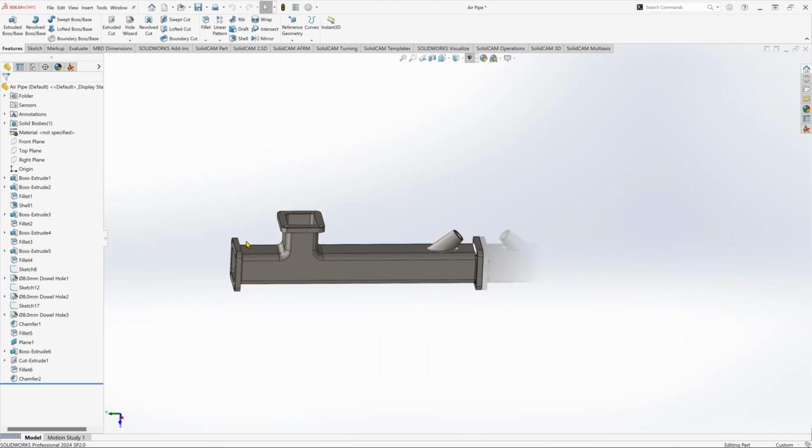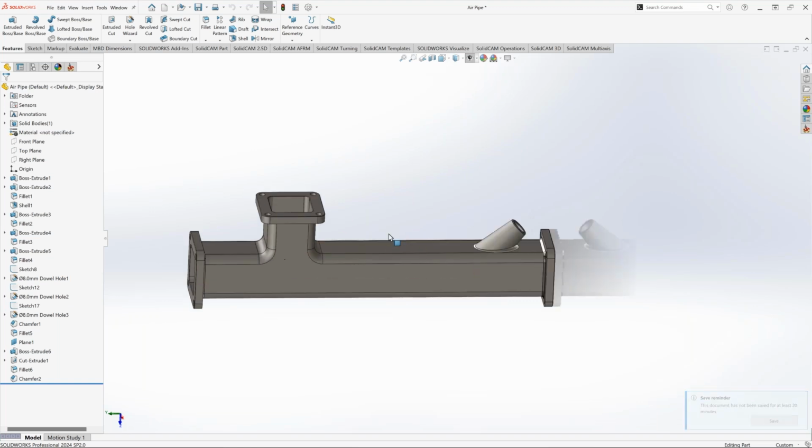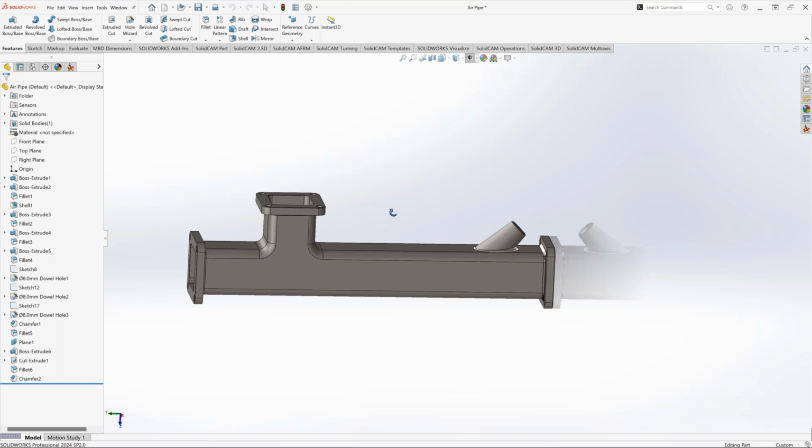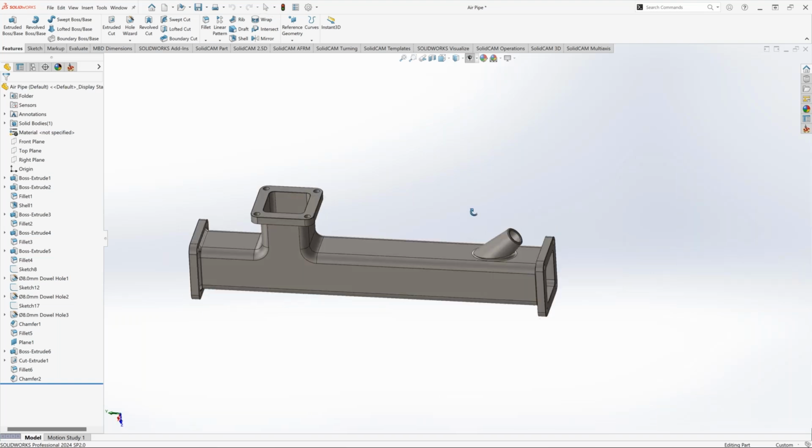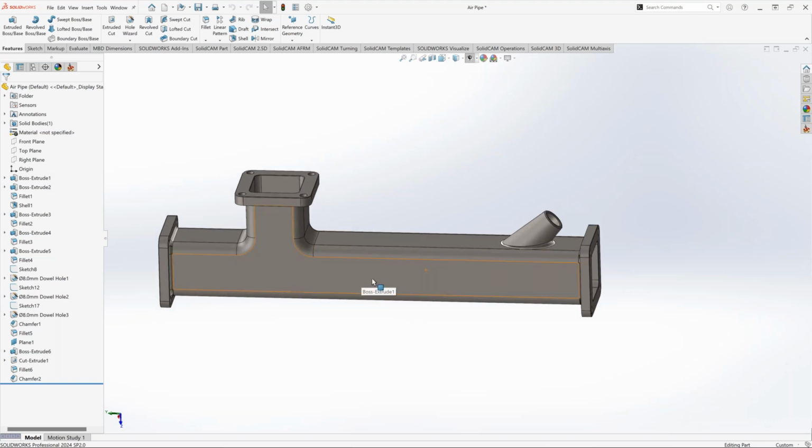If you don't want to disassemble it from the vises to keep the orientation, you need to create a very complex fixture for it. But we have another solution. You can buy, or maybe you already have, an angle head attachment in your shop, so you can use SolidCAM and angle heads to machine this part in one single setup.